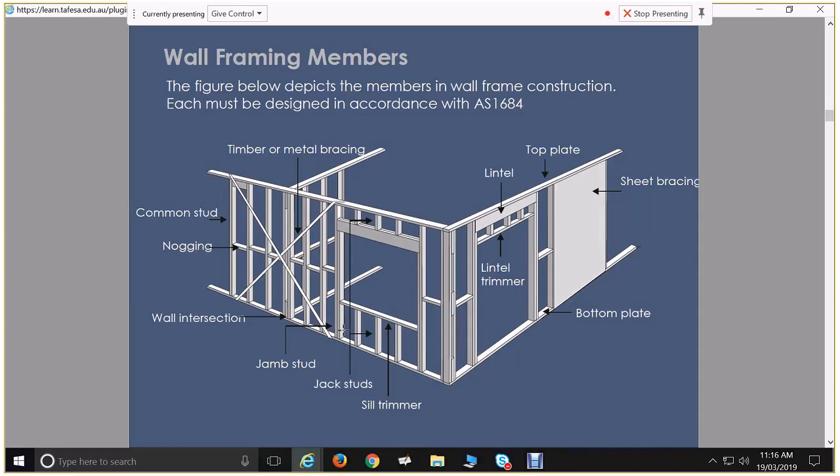Now, as I said before, your pieces of timber like your 90-35s are less than $2 a linear metre. We can sit down and spend 15-20 minutes designing, working out what these loads are going to be, and deciding, do we need one stud or do we need two studs? At $5 a stud, time-wise it's probably better to go: all openings have double studs. And then where you have even larger point loads, you go to triple studs.